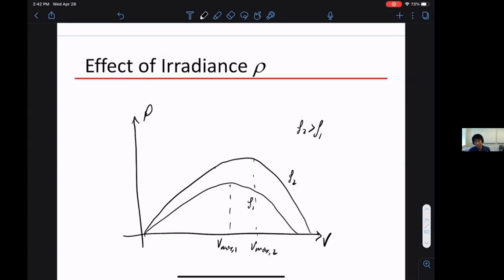If you look at a lot of inverter companies or companies that are selling you solar, a lot of innovation is actually coming from how to track this maximum power. How do I deal with this? How do I quickly track it? How do I reduce loss, for example, in my circuit? So these are as important, at least from our perspective, as how you make the panels themselves. That's something to keep in mind when people talk about the cost going down. It's both the cost of the material and the cost of, for example, the DC to DC converter going down. So we need both to happen.